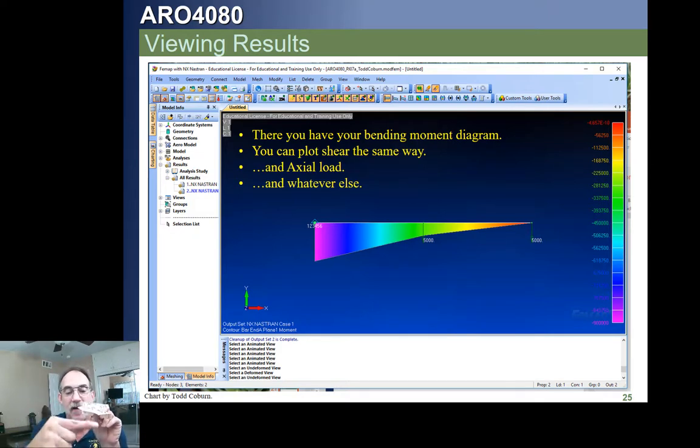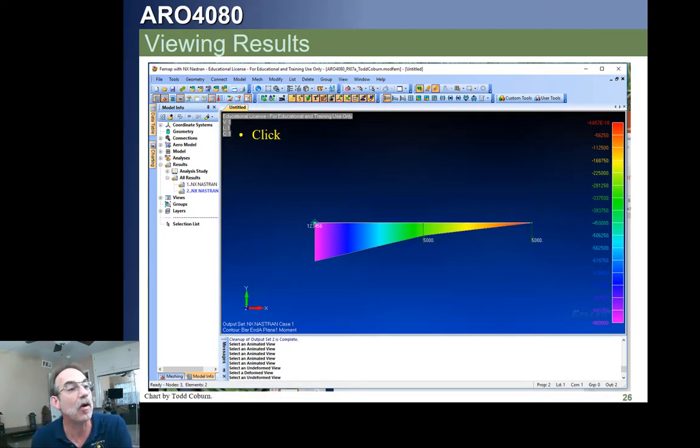Now if we define our properties, let's say going around a fuselage, all consistently, then the bending moment diagram will be consistent. But if we were careless and we made plane 1 this way for some elements and the other way for the other elements, then our beam, our shear and moment diagrams will be nonsense because they'll be flipping back and forth between different coordinate systems, basically. Okay. So this is a very powerful tool that is available in FEMAP.